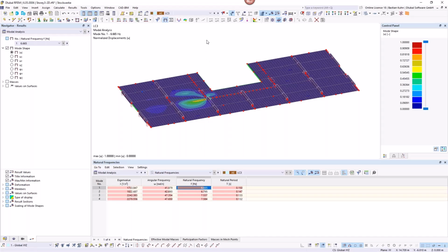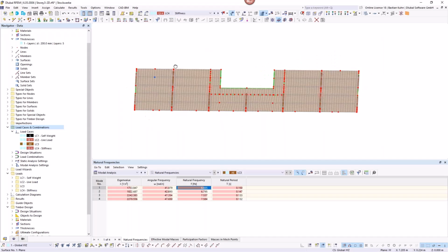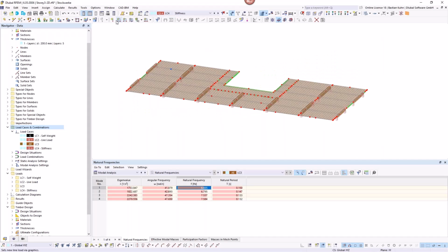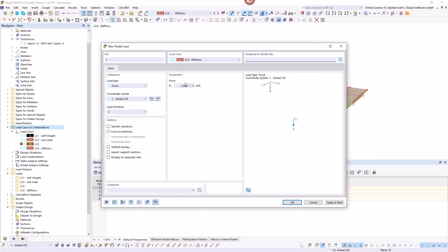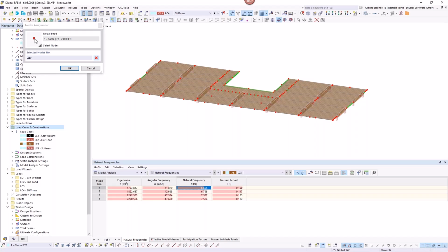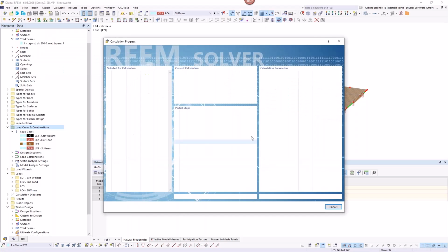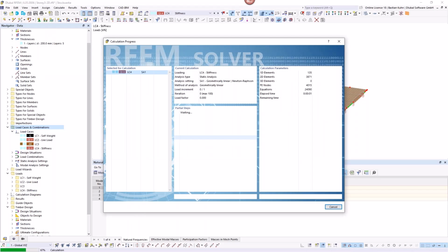44.8% overloaded. And now the second criterion is the stiffness criterion. Therefore, in the maximal deformed part, you have to define a single force of 2 kilonewton, and the deformation should be below 1 millimeter. And when this is fulfilled, your verification is done.